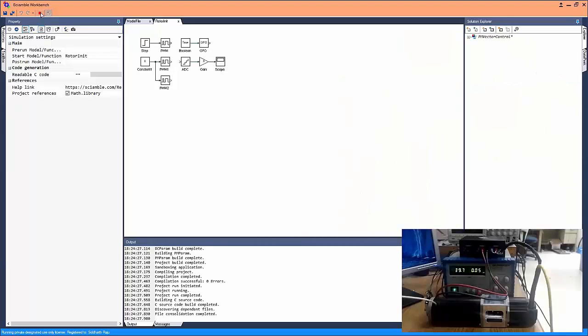Once we run this model, there is going to be a small rotation so that the rotor magnet aligns with the stator A-phase axis. And the degree of rotation is going to be determined by the number of pole pairs of the motor. This might not always be feasible in practical applications where uncontrolled rotation might not be allowed.